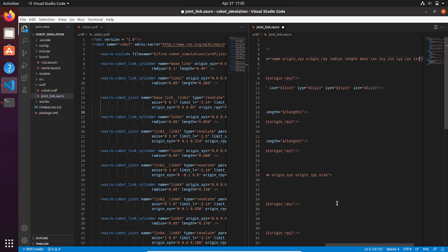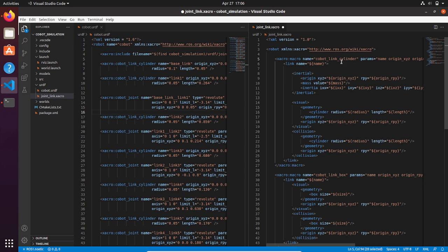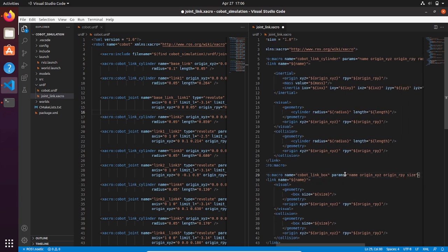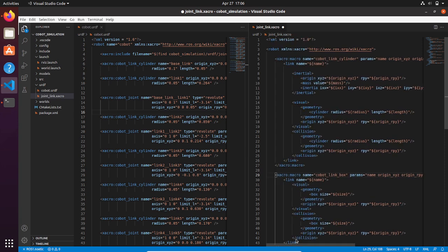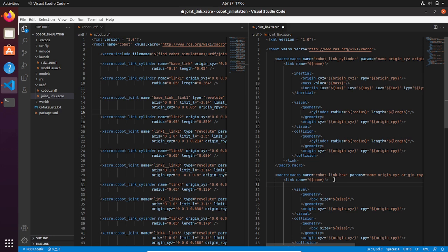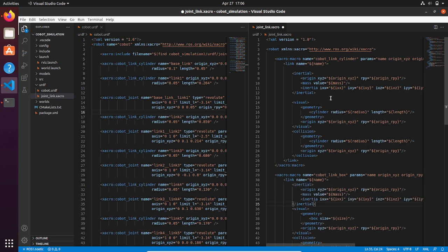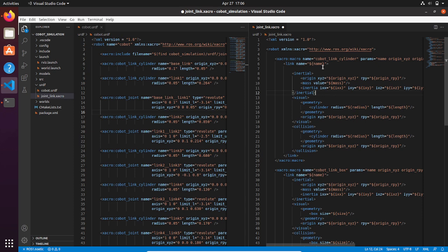But for this tutorial we are gonna calculate the inertia values from the formula on the wiki page. That's why we have modeled our links in such a way that they are reconducted to a cylinder, with a center of rotation that could be at the longitudinal axis, for example for the link 1, and for the other links the center of rotation is gonna be at the edge of the cylinder itself, for simplicity.